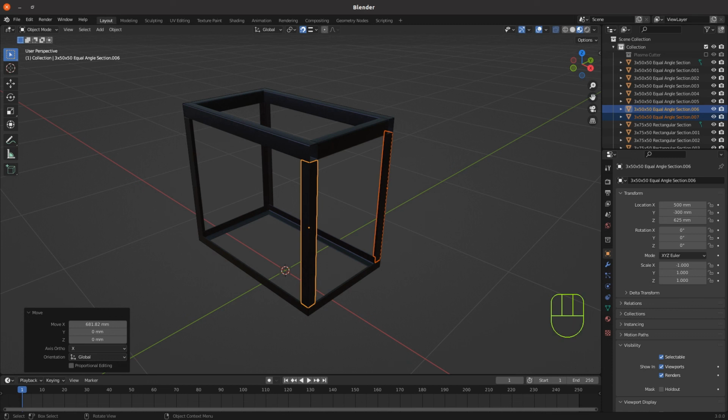If you have a library of standard conveyor parts, it can be very quickly pulled together, and it can be done in a much shorter time than I used to find having to constrain each component in a 3D parametric solids modeler takes. And you can rough out and prove fabrication assemblies extremely quickly and accurately, just based on setting up a quick reference cage to quickly bring and size the components into. But this finishes the outer frame of the table.